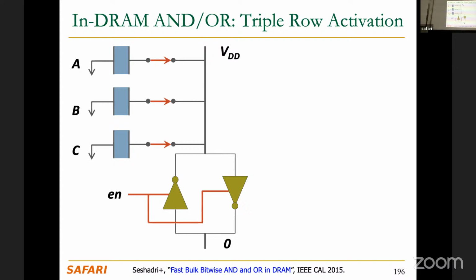Yeah, I understand that this is replicated in parallel, but you could separate the signal from A, B, and C into 3 separate bit lines, and then instead of having this circuit, actually have an adder or something like that, so that you don't have to do this translation. That will be more efficient for sure, and there are works that propose to do something similar to that actually. The problem is that including logic inside the DRAM chip itself is quite a challenging manufacturing process, and it's really costly actually.